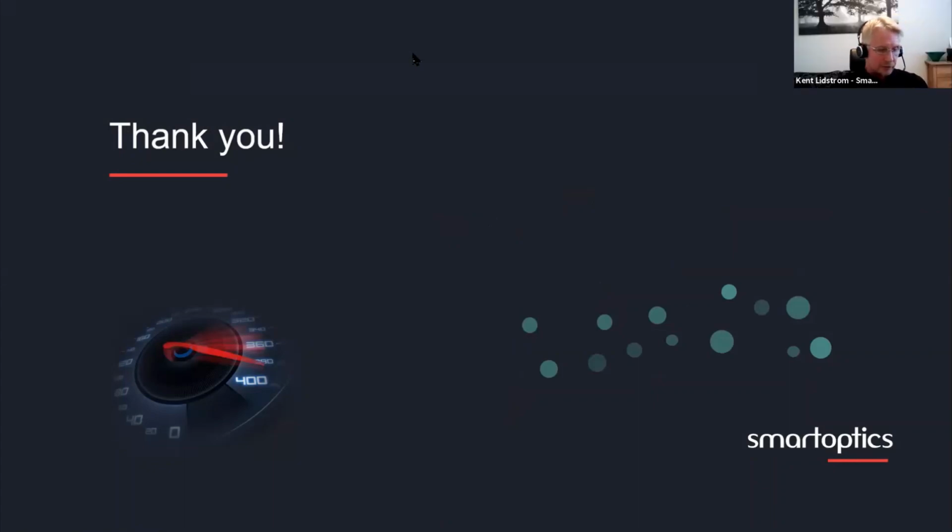That's a very good question. So it has a higher power class. So you have to make sure that the router supports that power class. The OIF-based standard has a lower power draw and a lower power class than the OpenZR+. So it depends a little bit on what optics you're using, but in many cases you will have a limitation, or let's say that you can only use the 400ZR optics on every 4th port or so. So it's very common that you have some kind of limitations on where and how you can use it. But you should be able to get the specification from your switch and router supplier.